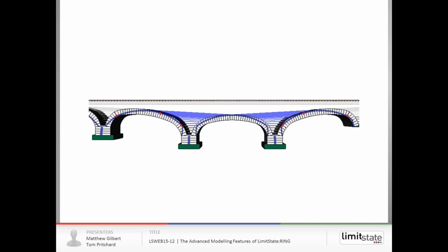That gives rise to quite an interesting observation: you can treat a settled bridge as an opportunity. If you get a good match between the model and your bridge, then probably the details you've input into the model are largely correct.